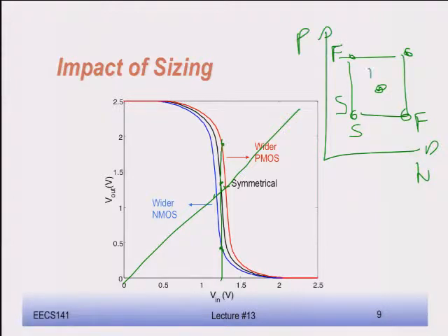This is the normal one. Then I can simulate my design. I know that my real design is going to be somewhere in that corner, in that square, because these are the extreme circumstances: the fastest possible transistor, the slowest possible transistors. Okay? So that's what we call corner simulations. And going to determine what the worst case is.